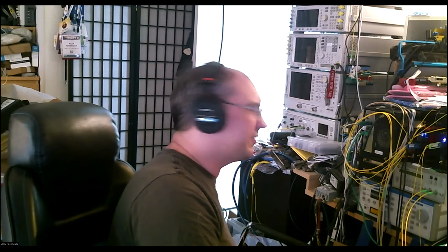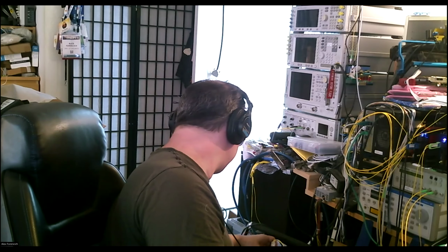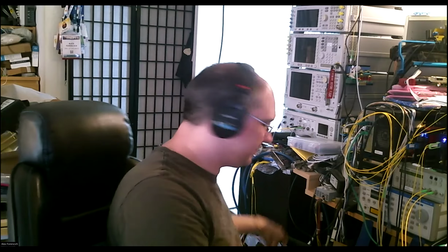These are branded Marvell, but I think the original company that made them is Inphi. They're two-lambda DWDM, so they squeeze two 50 gig subchannels into one DWDM channel. It's kind of funny, and the funny thing is these do not work in loopback. The output power is like minus 10 dBm, which is not enough. You have to go through amplifiers to amplify anything with them. But at least it doesn't hit so much.